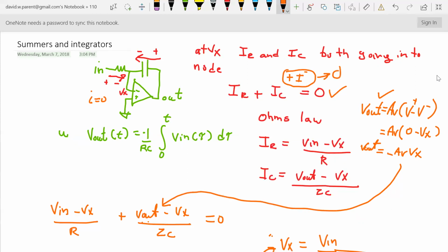I had this other equation that when I let that go to infinity, these two equaled each other and happen to equal 0. So what you'll hear me often say is, here's an ideal op-amp. I see negative feedback. This is 0. So since it's 0, I can just say right off after saying those two things, this node is equal to this node, and since one of them is connected to ground anyway, it's equal to 0. That's like the full-blown way to do it.